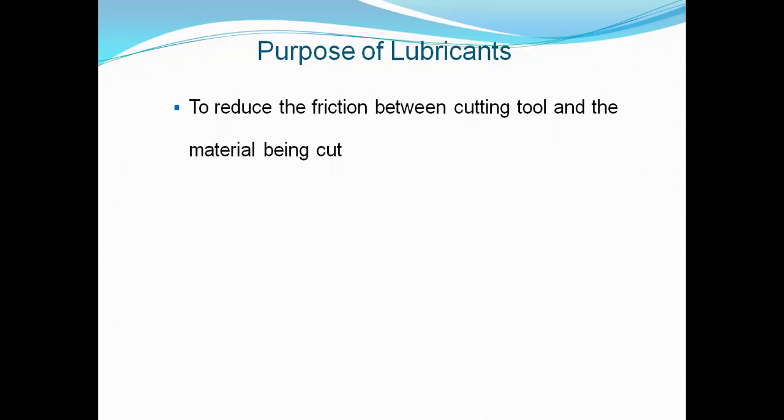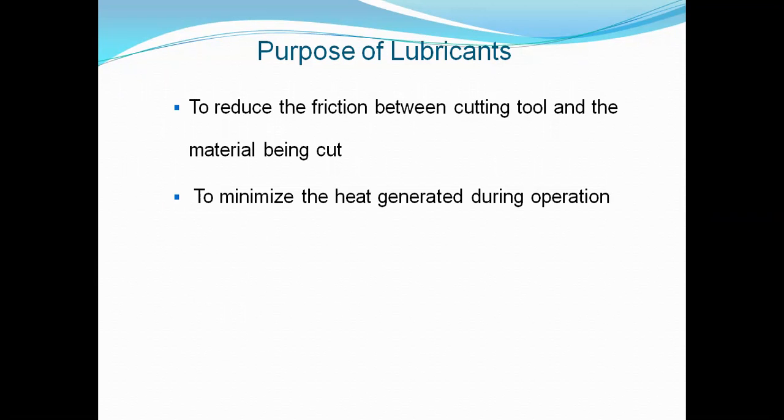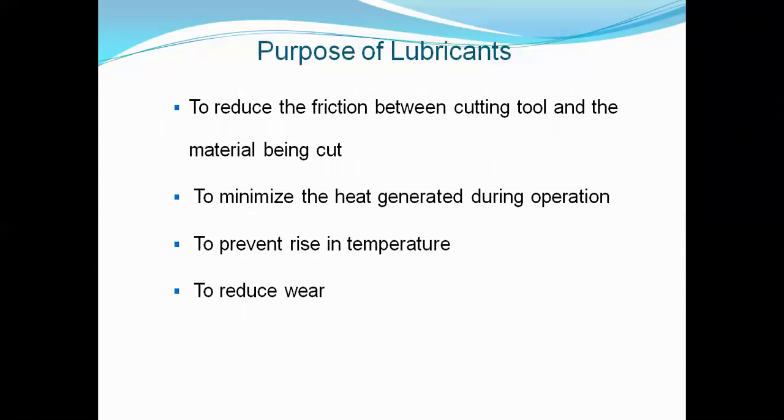And what is the purpose of lubricants? We know already: to reduce the friction between the cutting tool and the material being cut, to minimize the heat generated during operation, to prevent rise in temperature, and to reduce wear. Okay, so these are the purposes. Mainly we are reducing the friction between the two mating parts, and we can reduce the heat generated during the operation.